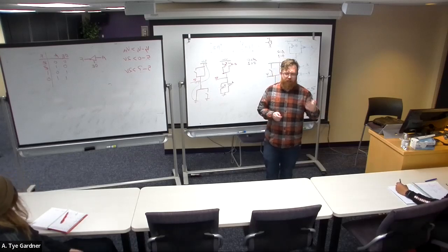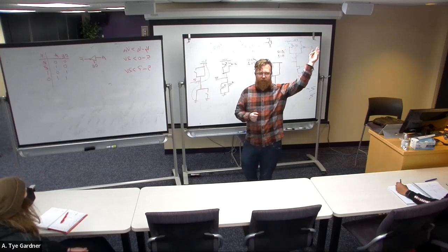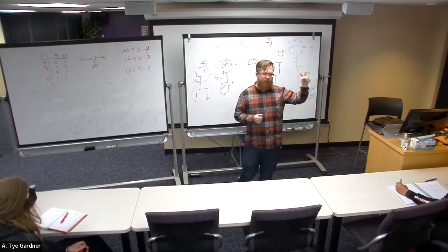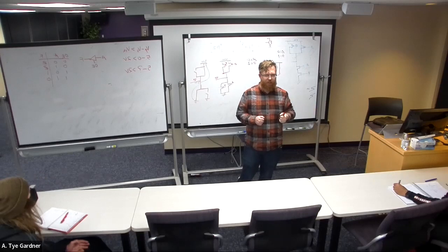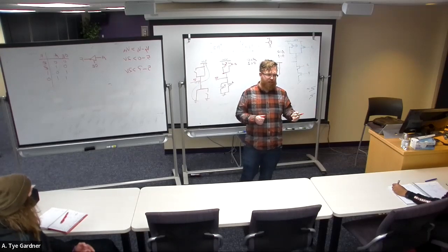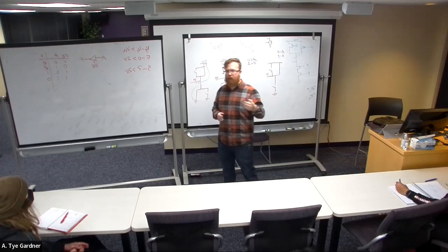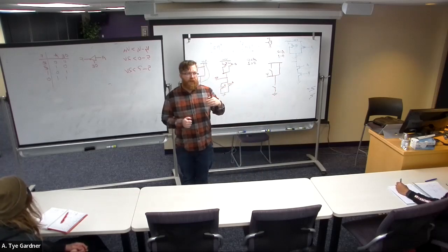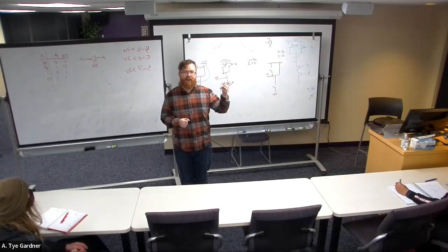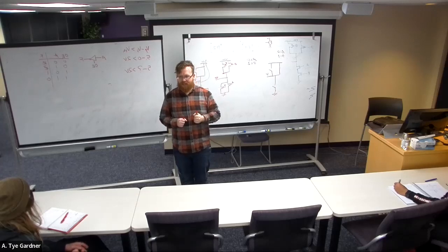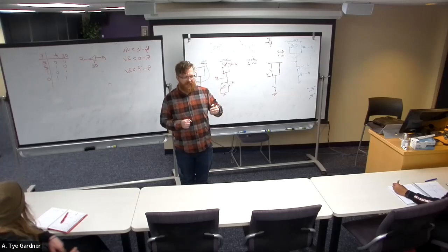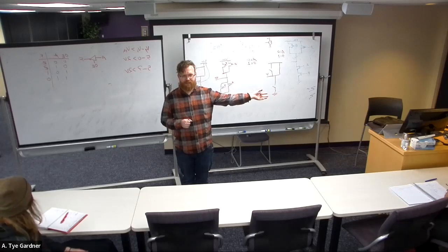And when I say frequency, like our power lines, right, the things that power this building and our homes and everything, oscillates up and down at 60 hertz. Okay, this is AC power, alternating current, with a frequency of 60 hertz. There are some devices, including capacitors, which is the one that you're most likely familiar with, that block electricity differently depending on how fast it oscillates. This is all impedance is talking about, is resistance over frequency. Okay.